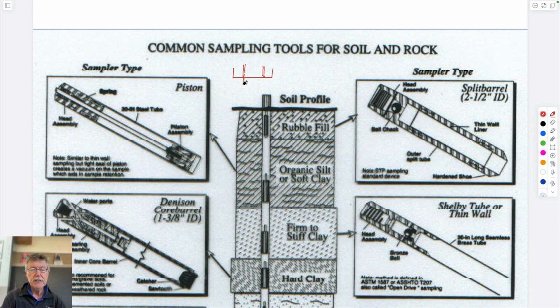When you push this physically into the ground at the bottom of the borehole, just pushing it, then what it will do is like a cookie cutter. It'll go in, maybe they're usually about 18 inches long. You'll push it down the full length just by pushing it, twist it to break it off at the top, and then pull out the whole sample. That's one way of sampling.